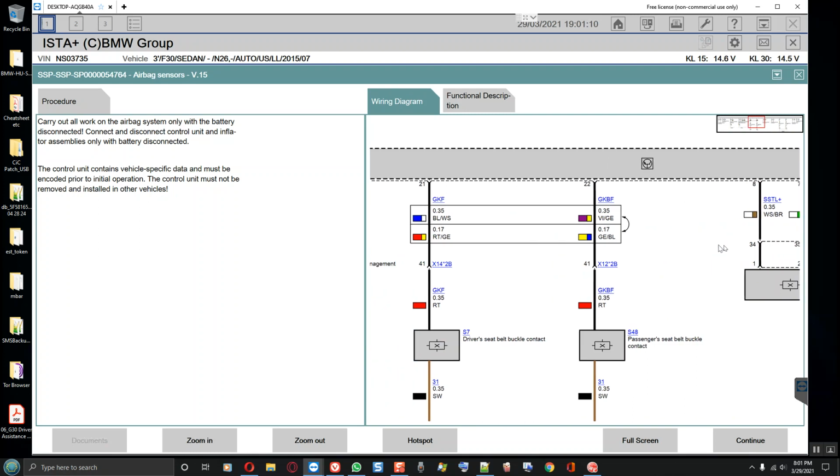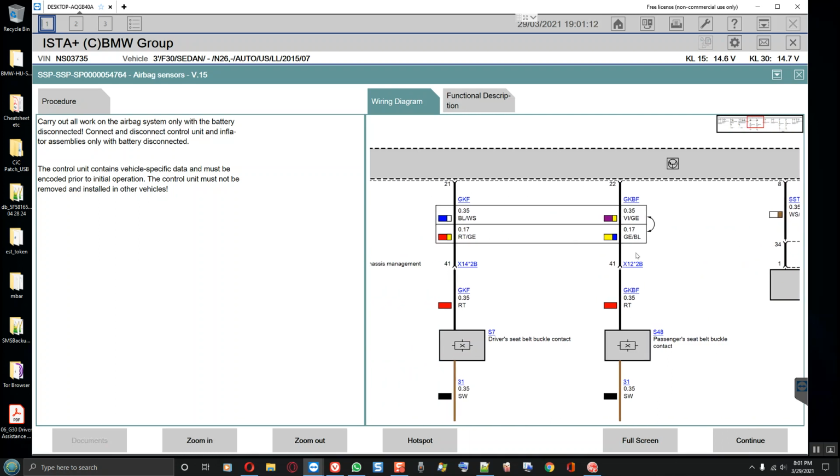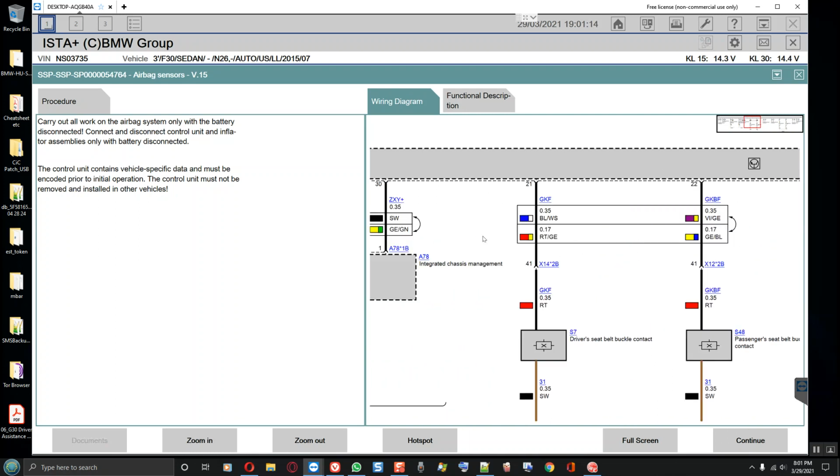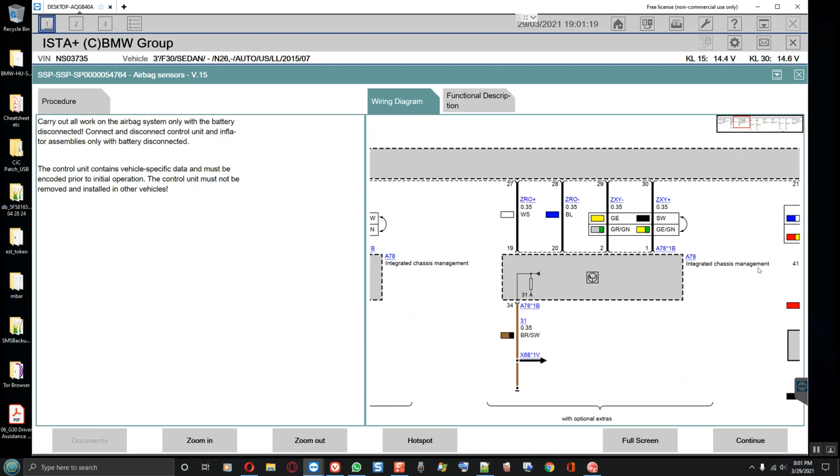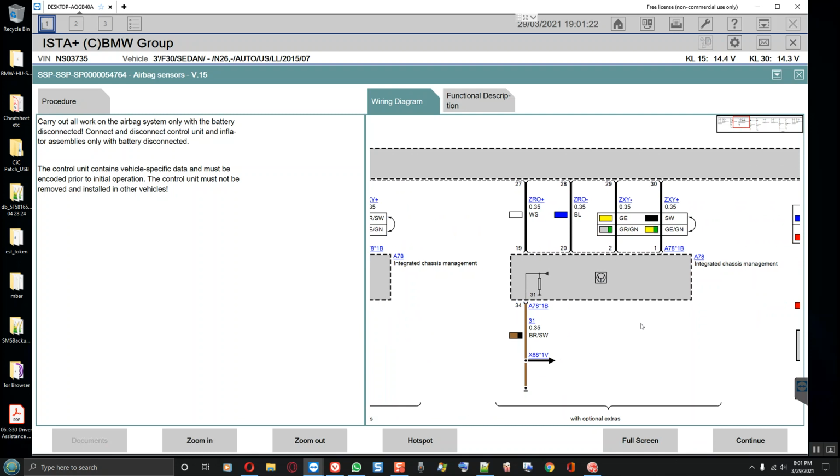Okay, man. That was the other thing I was thinking: if it was a coding issue, then it wouldn't have made sense that it would give that open circuit fault. You think it would be something different. No, open circuit is something physical, not something software. That's what I was thinking, but then when I couldn't find anything in the wiring... No, sometimes you miss something in the wiring. That is where you have to not doubt. You have to really look at if you really missed something. That is where you have to go back over that again.